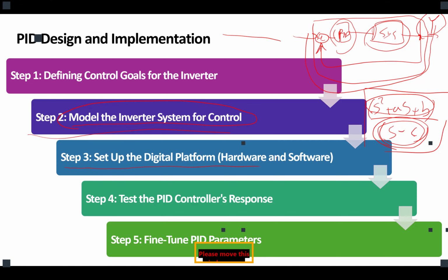If it's analog, KP, KD, and KI can be achieved at specific values by tuning the R, L, and C in your analog circuit. So you could translate those optimum values into calibrated values for your circuit design. Is that clear? So the next step is circuit design.